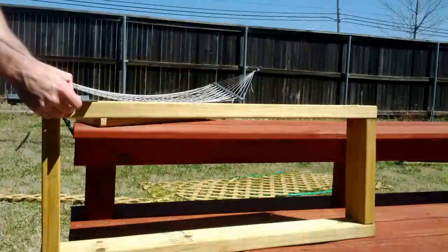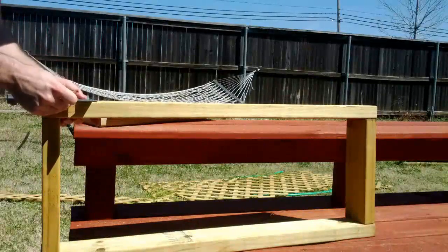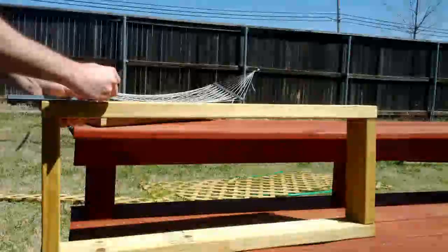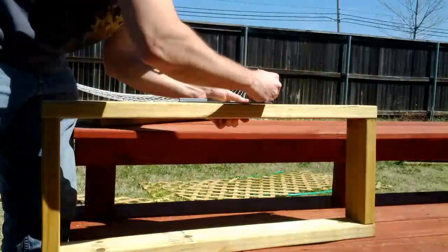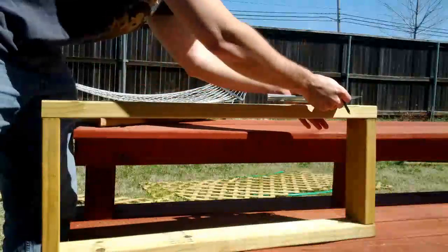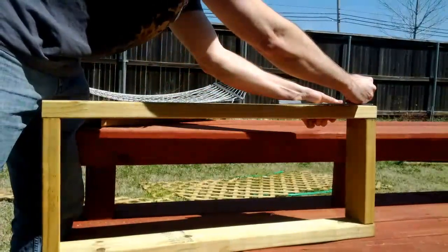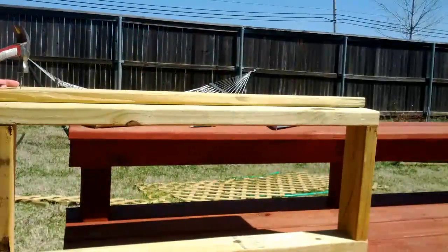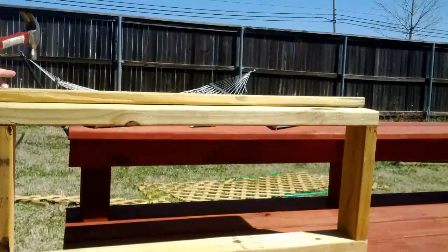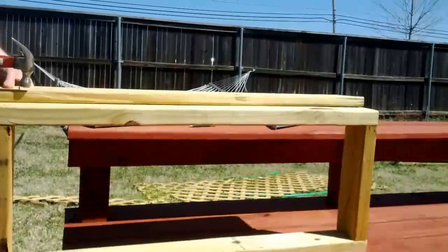And I want to mark with my square here. I think it was about 2.5 inches up. And I mark that down so I can get the top frame of the deck boards that I'm nailing to the top part of this box. Get them all straight and even. Let's get that hammered on there with those smaller nails. They didn't want to be too sturdy.